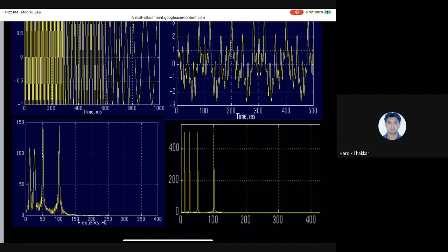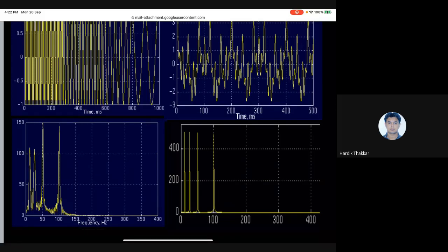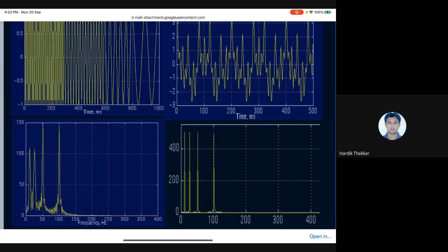From this kind of analysis, you can easily tell that in the right hand picture, as all frequency components are present at all times, you don't see any jerky nature. And as all frequency components are present at all times, all of them contribute an equal amount of information. That's why the heights are the same. In the left picture, the heights are not the same because all frequency components are not present for equal time. So 50 Hz and 100 Hz are present for a longer time, and 10 Hz and 25 Hz are present for less time. This is what it says, right?